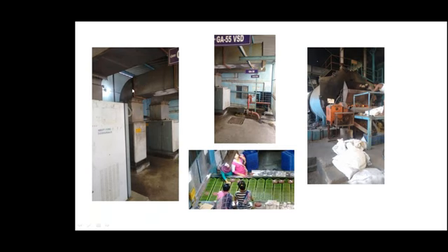Now, what we have done is, this is at 90 degrees. So 90-degree air is vented out here. And adjacent here, you see this window. Beyond this wall is the dryer. So all we need to do is to tap this. See, these are the ducts you see. So you have to take these ducts, take them inside the dryer room and put them in the dryer.